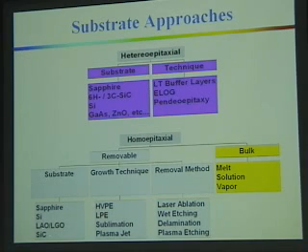And I will show you that we were able to, with lithium aluminate and lithium gallate, achieve self-separation. That is, they would separate upon cooling due to the thermal stress, the mismatch of thermal expansion coefficients produced a stress that caused and promoted the delamination. The silicon is very cheap for the substrate, and it's very easily removed, etched selectively relative to gallium nitride.